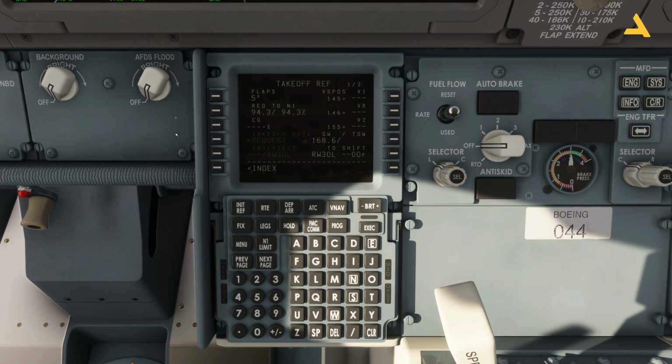Again, if you have a takeoff performance calculator, you can have the optimum flaps for the takeoff. But remember that flaps not only provide lift, they also provide drag during the takeoff. So you want to go with the optimum settings of the flaps. I can even set it to 10, and you will see these speeds for the takeoff will change. So let's go with 5 flaps.